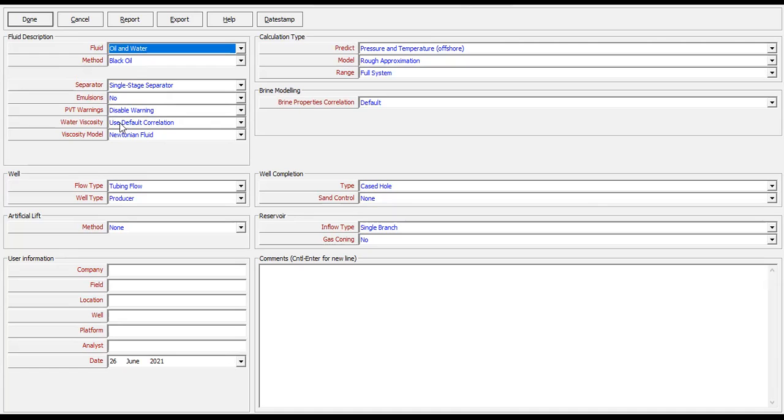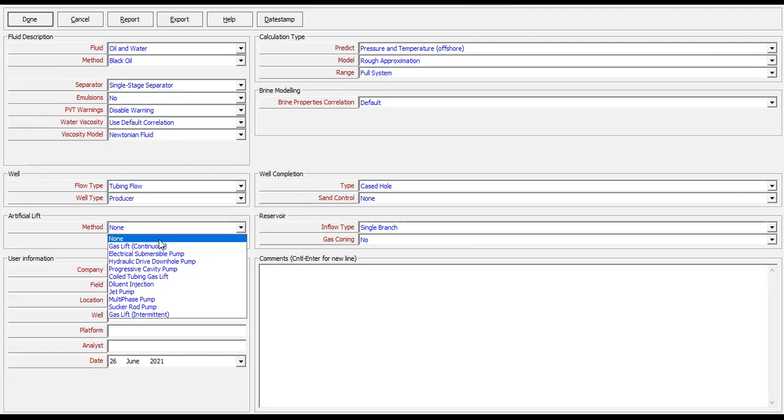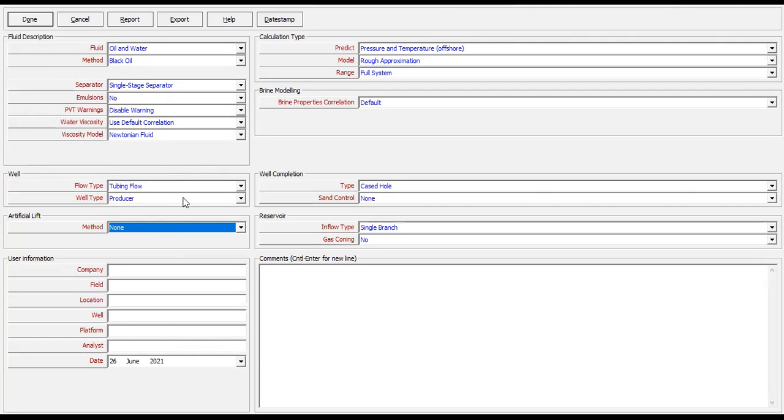Water viscosity, we will use correlation. And viscosity model, Newtonian fluid. Flow type, tubing flow. Well type, producer. Okay. Artificial lift, none. We will not do any artificial lift analysis or design here in this video.